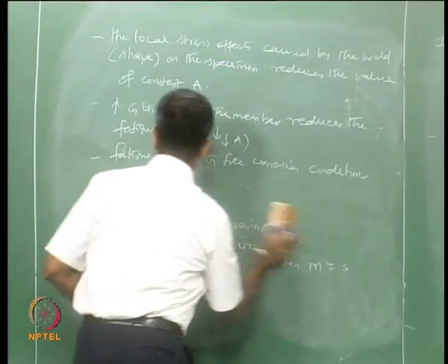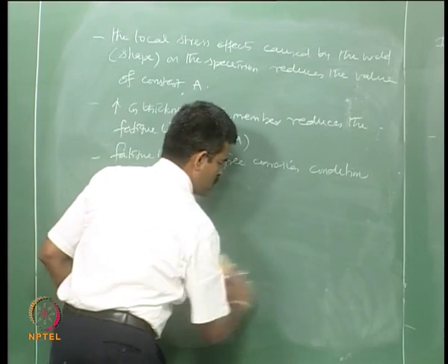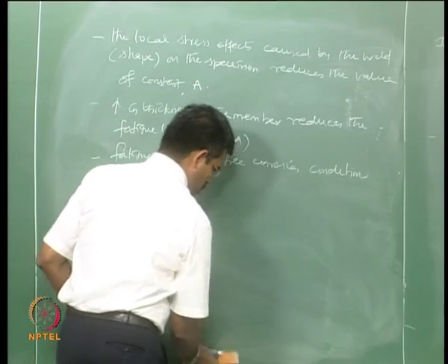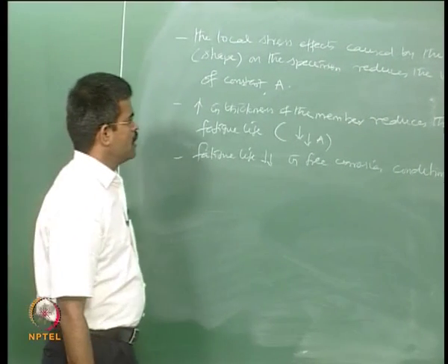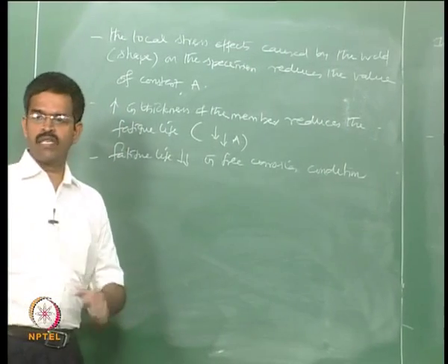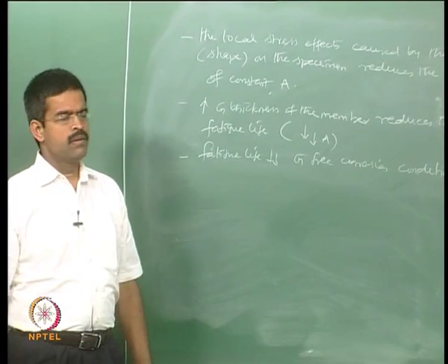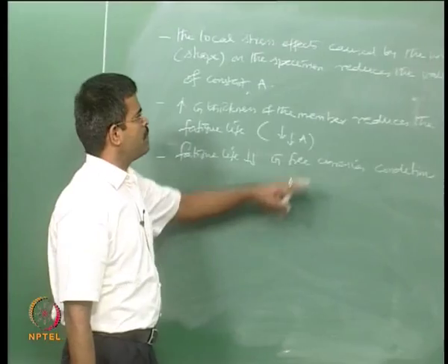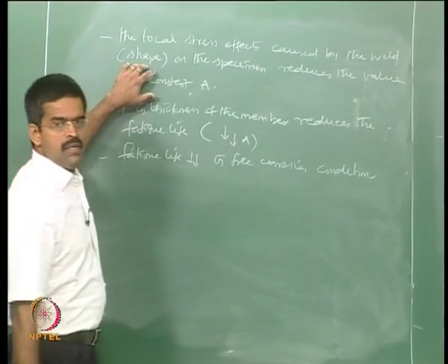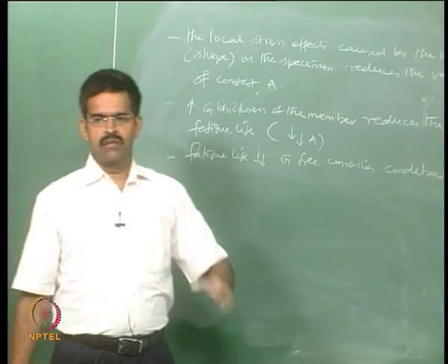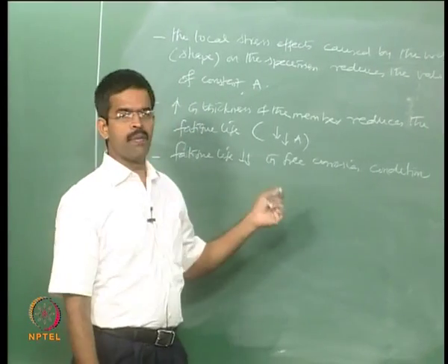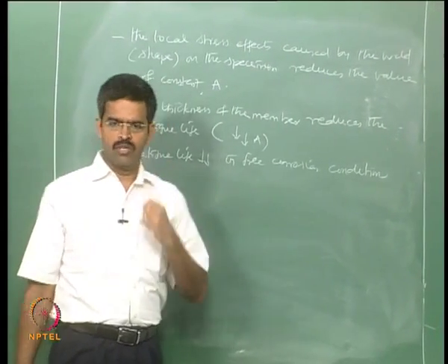Many international codes have focused SN curves to be very specific on tubular joints, because as you know, SN curves are influenced by the type of specimen and they are also influenced by the shape of the weld. So there are specific curves generated by conducting experiments on T joints or tubular joints.